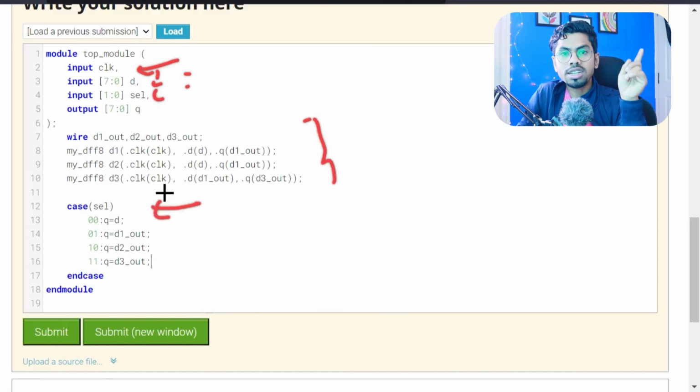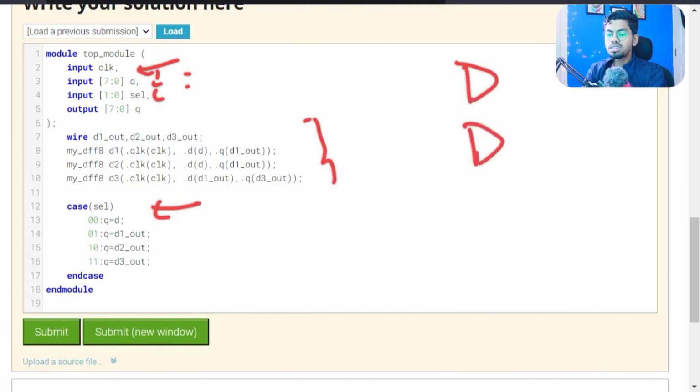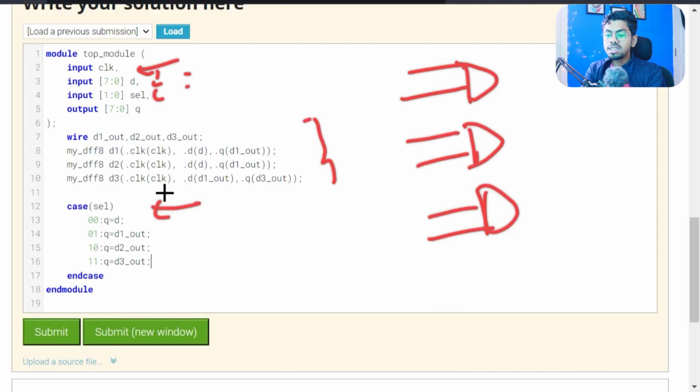As I said in our first class, in Verilog you need some method by which you can concurrently run different blocks of code, because that's how hardware works. If your hardware has 3 AND gates and you are giving input to them, then these 3 AND gates will work at the same time, right? That's what we need to achieve in our Verilog code. Otherwise we can't model hardware.